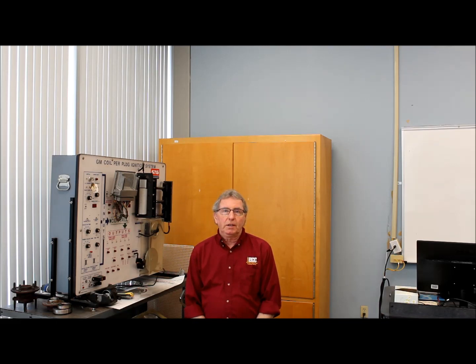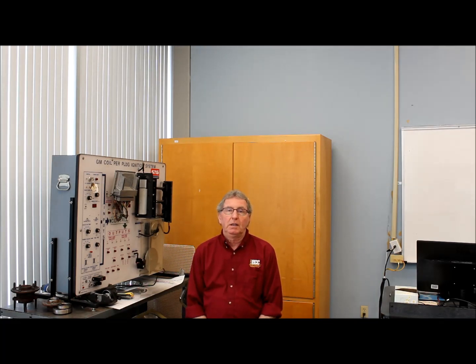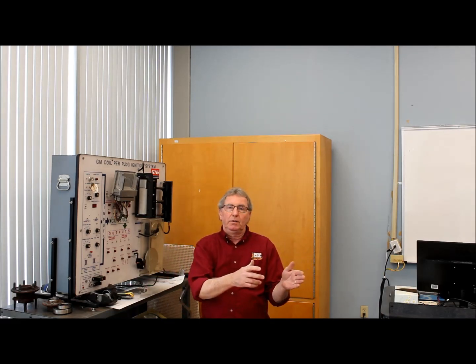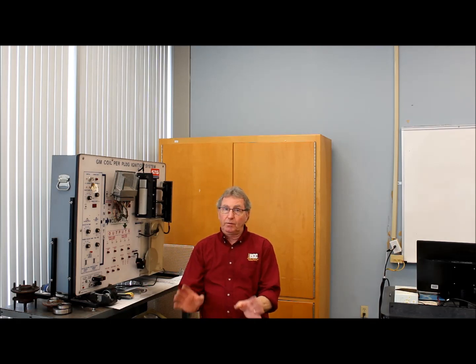So we'll do a little bit of looking at what those wires look like, how they're configured. There's a couple different ways they're set up. We have star configuration. In a star configuration, everything comes back to a central point. And then we have ring configuration. In a ring configuration, the network goes from this module to this module to this module. So during the lecture portion, I'll show you this on ALLDATA. And in here, I'm just going to build very, very crude examples of what those networks actually look like.